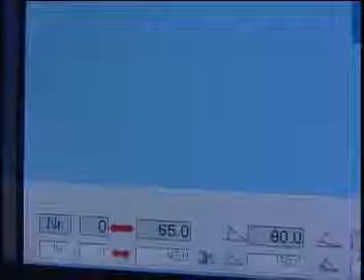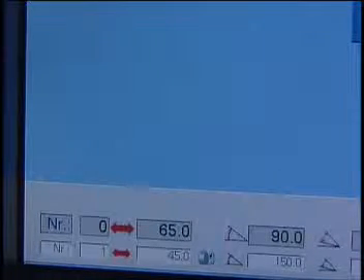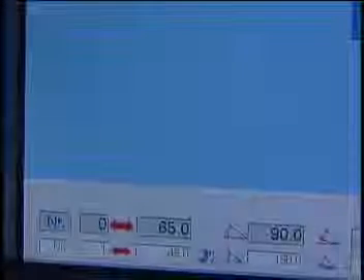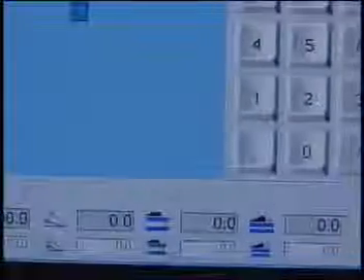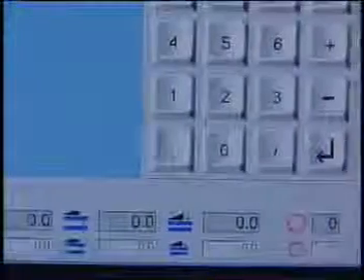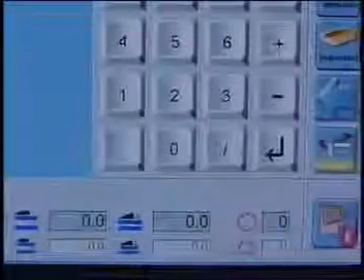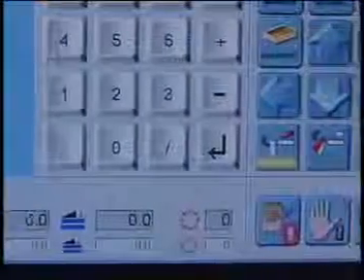At the bottom of the screen, you will find the actual and the following program line of the present profile. Each line has a sequential number, a value for the back gauge, symbols for material rotations, and a column for the bending angle. The bending angle correction compensates the material spring back when doing radius work. Upper beam lift up is important when parts must be turned around. And so is the column for open hems, and the final column for the number of loops to form radius.